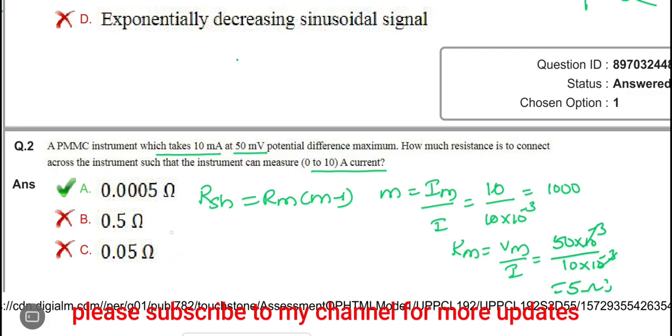Now substituting in this formula, RSH is equal to meter resistance 5 and M is 1000 minus 1. Okay, mistake here. It is Rm by M minus 1. Make a correction: Rm by M minus 1. So it is 5 divided by 1000 minus 1.